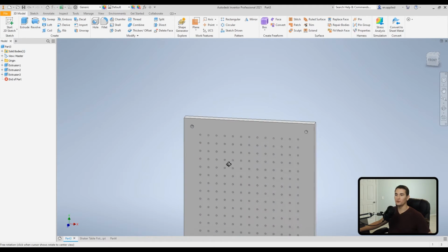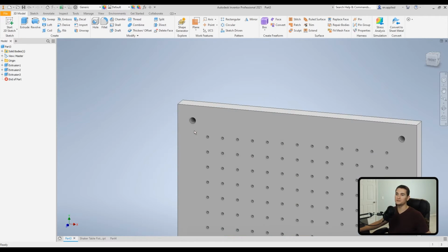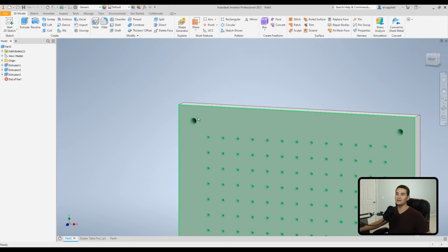Okay, so now we have a through hole, but we need to create a space to accommodate the larger diameter for the head of the socket head fastener. So what we're going to do is create a cut halfway through the plate that allows the head of the screw to go below the surface so that we don't create any sort of interferences with any parts that we may attach to the top of this plate. This is a huge thing you want to think about. So we're always thinking 3 steps ahead or even more sometimes to make sure that we don't have any interferences or any problems within our test equipment. So we'll go ahead and do that now.